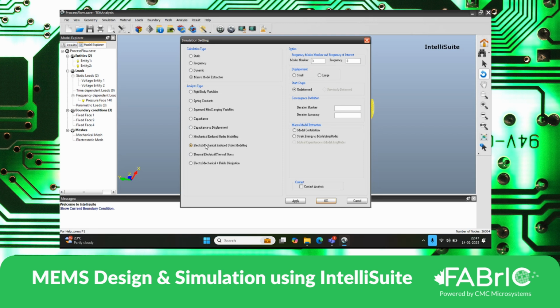So we would have already completed the three simulations, that is static, frequency and dynamic analysis, and would have reached a stage where we have a fair understanding of our device working. And now this is where we do the model contribution. So in the case of electromechanical reduced ordered model simulation, we do the model contribution in the first place.